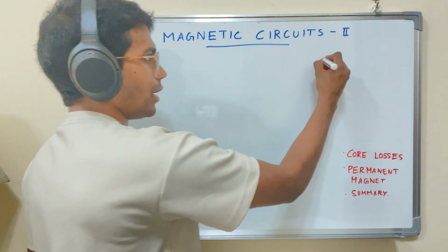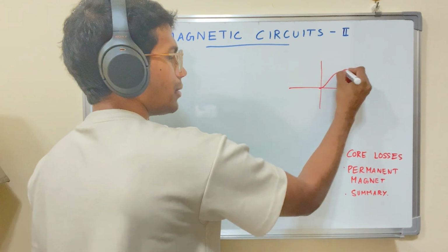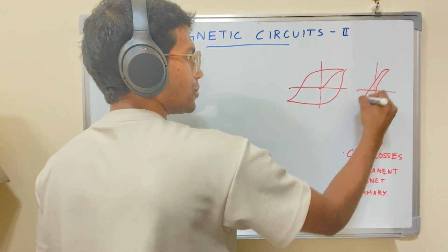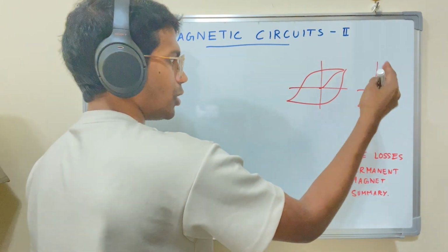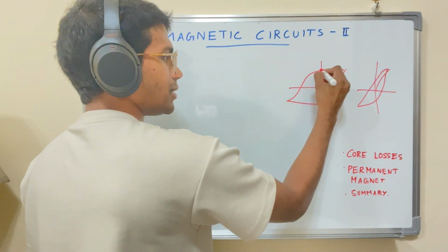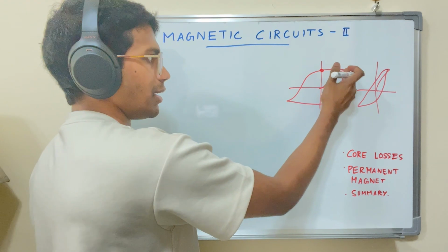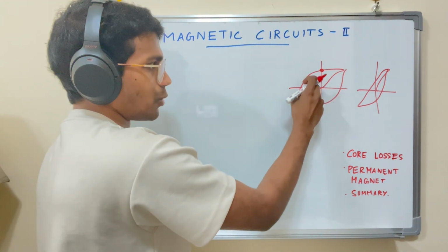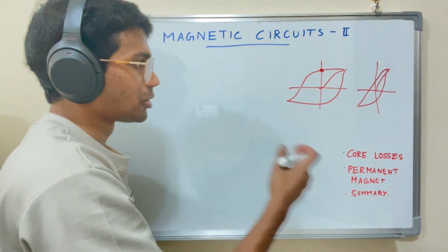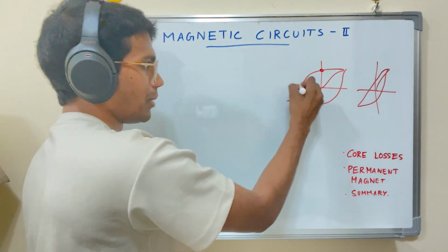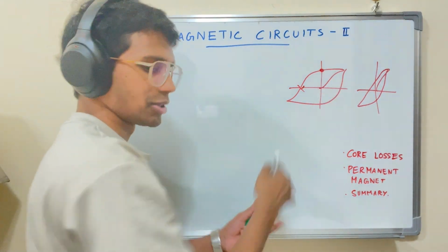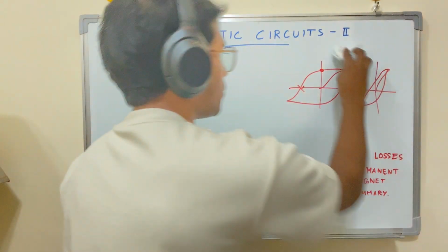Of course, if we have a material made of hard iron or a hard material and a material made of soft iron or some soft material, the losses are going to be much higher for the hard one. And this is the retentivity or the remanence, where if the H is taken off, how much is remaining? And coercivity is this point where how much do you need to coerce it to demagnetize in the opposite direction. And these two values are much smaller for a soft material.